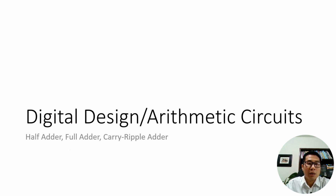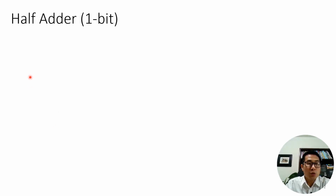Okay. Now, the first one over here is called the half adder, or 1-bit adder. So why is that called half? Because when we add a bit with another bit, it's going to produce a sum and a carry. But it is called a half because it doesn't care about the carry that may come from the previous bit.